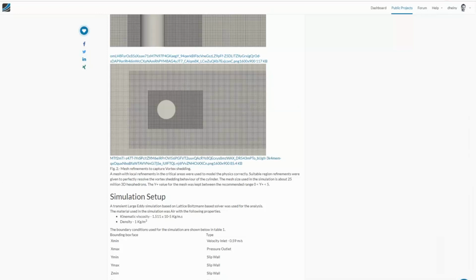Okay, two more. I think those are small ones and can be answered quickly. One question is, does this LBM solver actually solve two-phase flows? Right now, no, it does not, right? It has really been built for aerodynamics, and this is what it does. So this is the initial go-to-market. Again, I would encourage everyone to note that there are multi-phase flow solvers in SimScale, finite volume-based, so you can run multi-phase flow analysis on SimScale, but with this specific Lattice Boltzmann method, you cannot right now. Last question, and then I suggest we wrap it up there, and I'll try to cover the rest of the questions by email or in subsequent conversations.